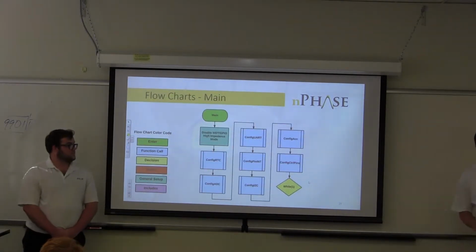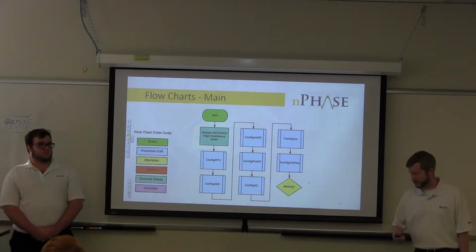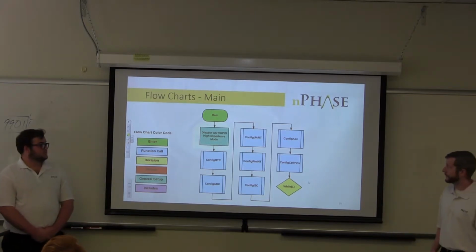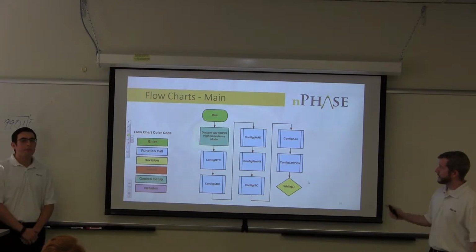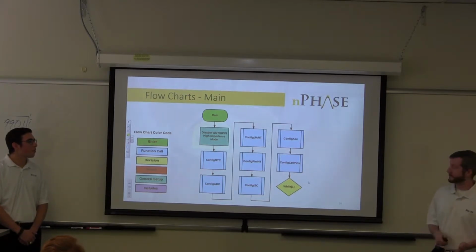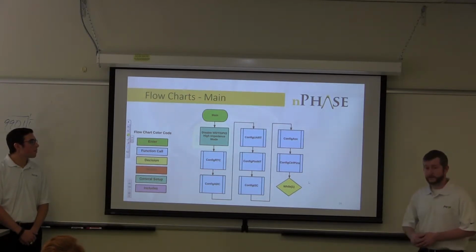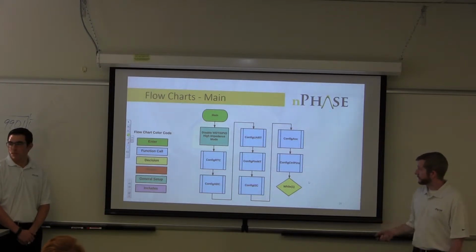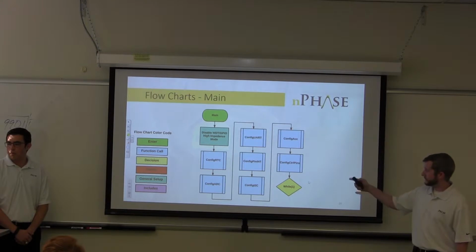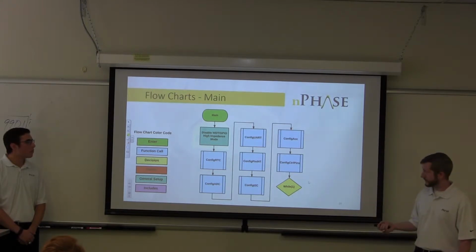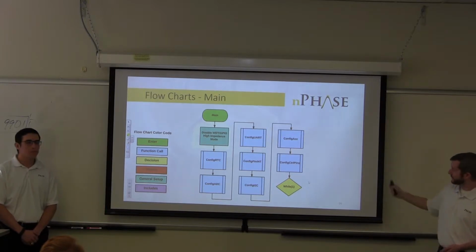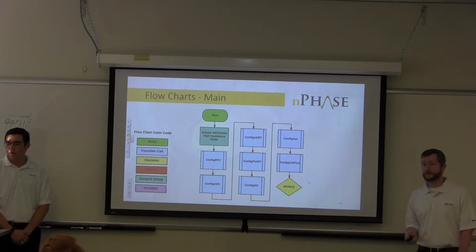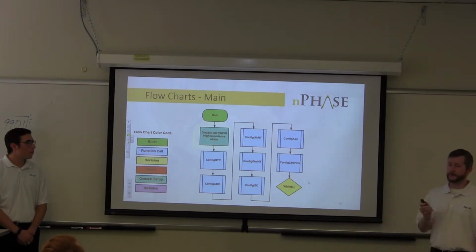Next we have our flowcharts. Okay, so let me go over our software flowcharts for the MSP430. First up, we have our main, where we need to disable our watchdog timer and also disable our GPIO high impedance mode. Next, we're going to be calling all of our configure functions, including our real-time clock, ADC, our UART, our pin int, which is our interrupt coming from our accelerometer, our I2C communication, our accelerometer itself, and our control pins going out to power our SimpleLink and our Wheatstone bridge.